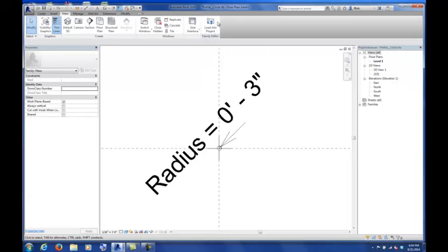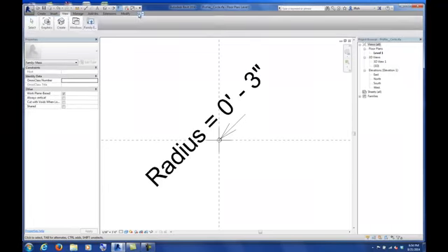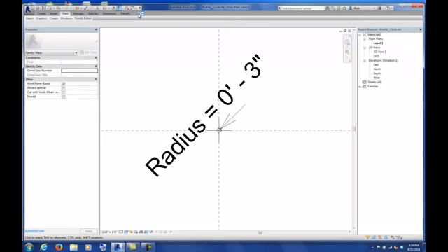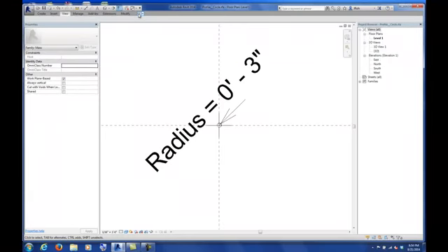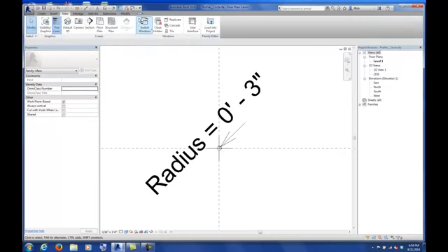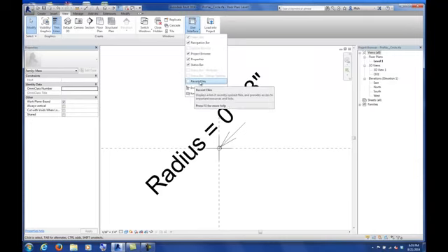Another thing that happens from time to time that I just want to get out of the way is, you see this little button up here? It's hard to see. It's kind of like this up arrow. If I keep selecting that, look at my icons. They collapse into different ways of displaying your icons. So if you happen to open up Revit or for some reason you hit that button and you notice your Revit looks a lot different than you've ever seen it before, and people start freaking out when that happens, most likely it's because of that button, and you just need to cycle through until you get to the way that you like to work, which is pretty much this tool ribbon method that we're going to be using throughout the class.